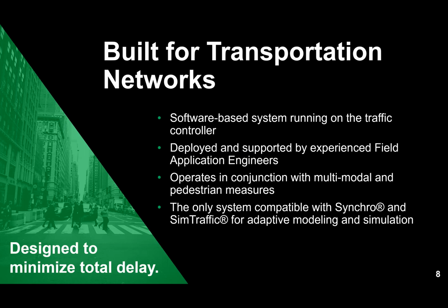So Trafficware has an ATMS central system that some agencies may use citywide throughout all of their intersections and corridors. Or that agency may only use our SynchroGreen in one corridor, in which case they would get the ATMS foundation that allows for any triggering systems and allows for maximum flexibility. A triggering system is an if-this-then-this function, meaning if something is happening out on the roadway, the SynchroGreen can adjust.